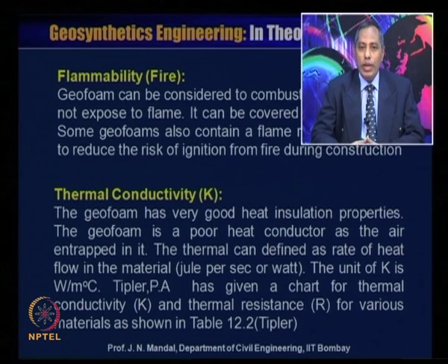The geofoam is a poor heat conductor as air is entrapped in it. Thermal conductivity can be defined as the rate of heat flow in the material, that is joule per second or watt. The unit of thermal conductivity K is watt per meter degree centigrade.